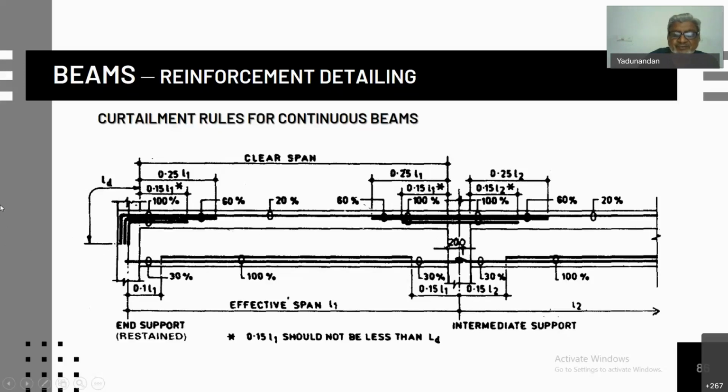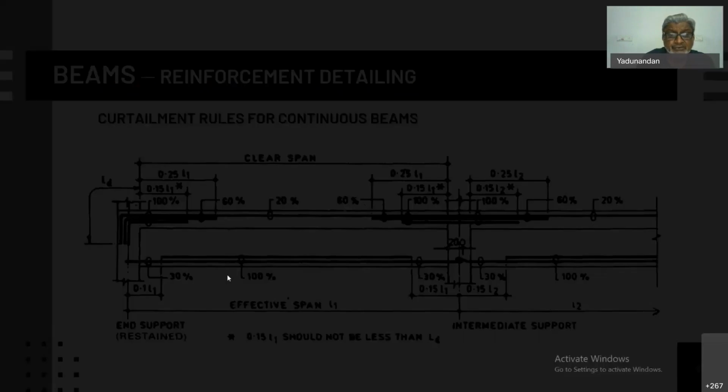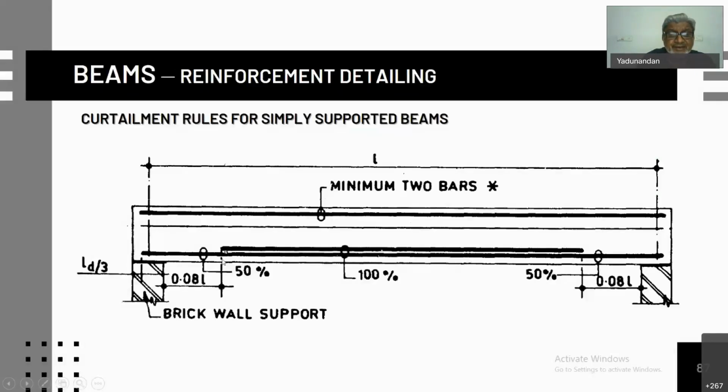In case you have a doubly reinforced section, it is necessary to avoid the reinforcement designed by the compression reinforcement percentage calculation that you provide. So this is the reinforcement data. You see that at 1L distance the bottom bar is stopped here, and the top minimum 2 bars are provided at the top. That is also a precondition that you all know.